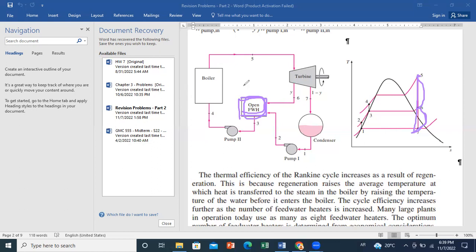If I say that it's insulated from the surroundings, so I can say that there is no Q to the outer environment. So I don't have Q lost, and I don't have Q gained. So the sum of Q dot, lost plus gained, is 0 because it's adiabatic. And I don't have a work rate. It's not a turbine, it's not a pump. So also the sum of W dot is equal to 0. So I just have the flows of energy.